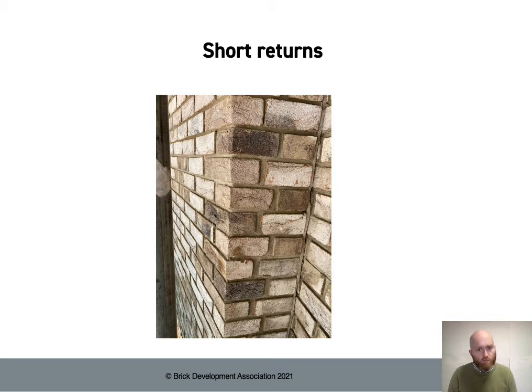and you can see the compressible filler within this area. Actually, when the mastic has been applied, you colour match that mastic to the mortar colour, and you just don't really read it as anything hugely different from your normal bonded corner.